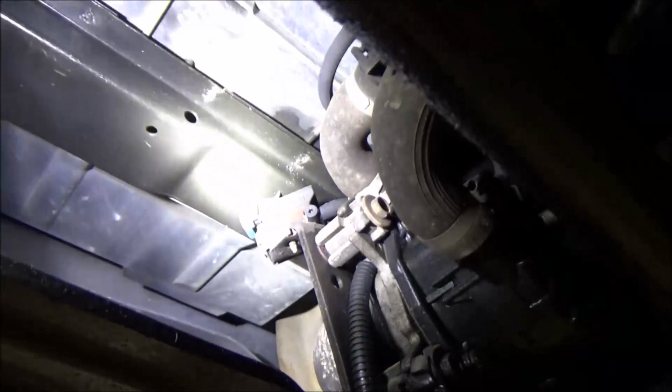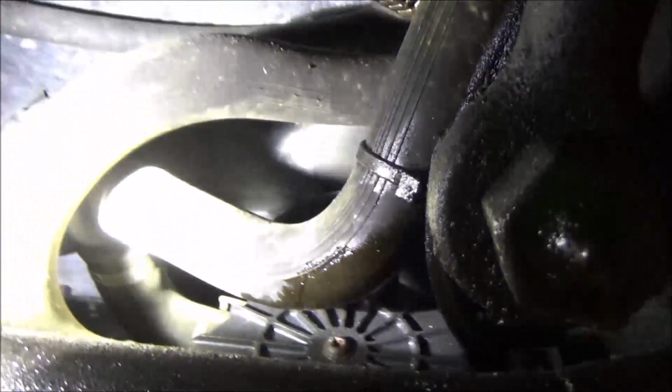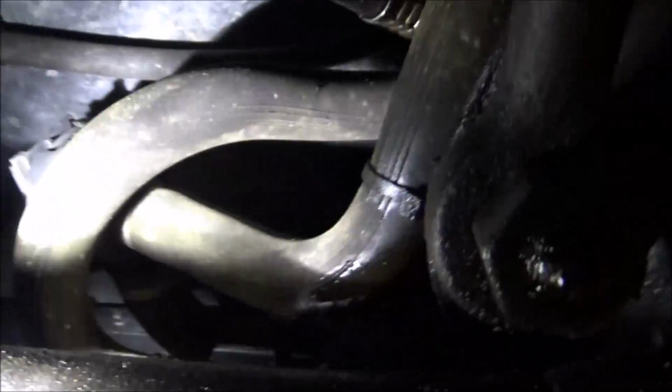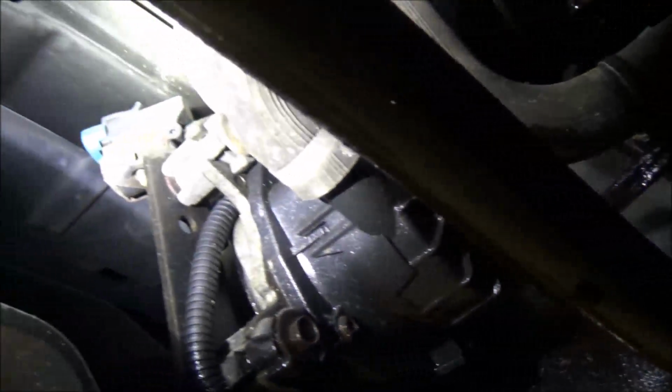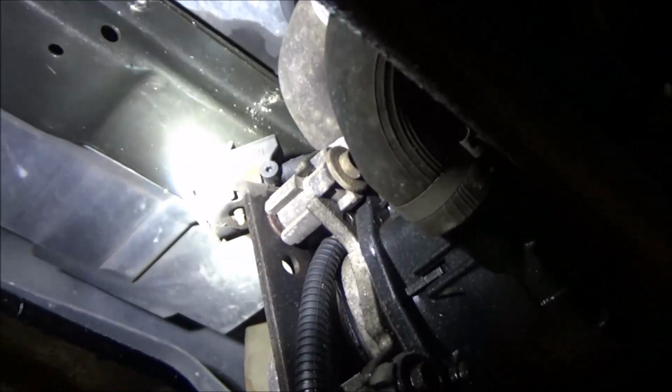As far as the solenoid, basically what we're going to do, this is that vacuum solenoid that controls vacuum to this actuator here. This actuator is going to open and allow flow to come from the motor all the way up this long hose, all the way up to the top of the vehicle and to the exhaust manifold. So we're going to focus on this solenoid here for now, and we're going to use that functional test, and we're really just trying to prove the relay out.